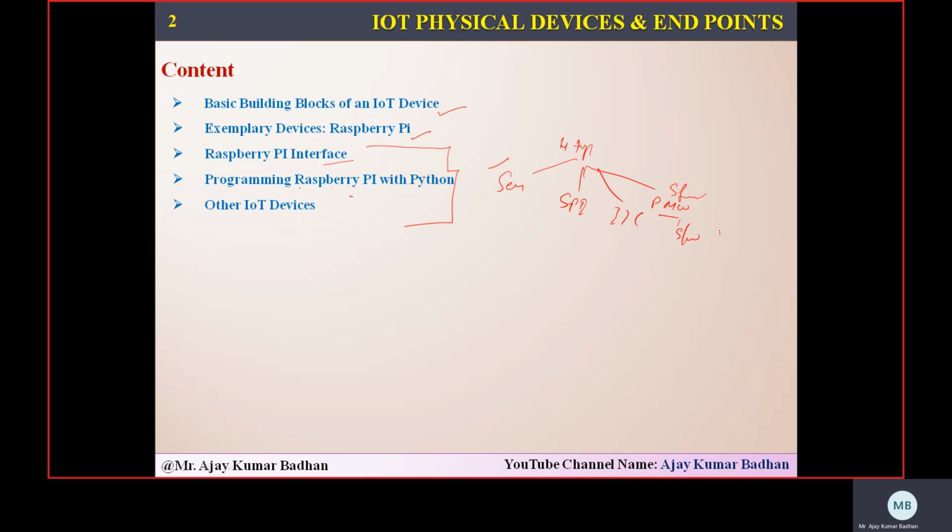So these are the standard pins. In this we have software related and hardware related. Software is present in all the pins. Hardware related, we discussed some 4 different types of pins, right? And in the same way for I2C, we have seen some pins which support I2C. What do you mean by I2C? I think people are familiar now: I2C is nothing but inter-integrated circuit. It is used to connect other sensors to a Raspberry Pi. For that we use this I2C.